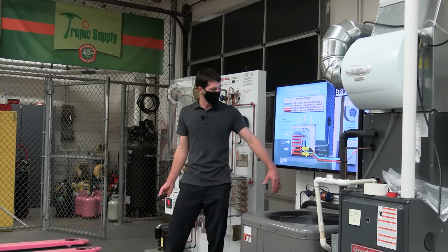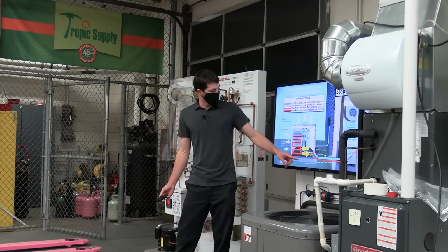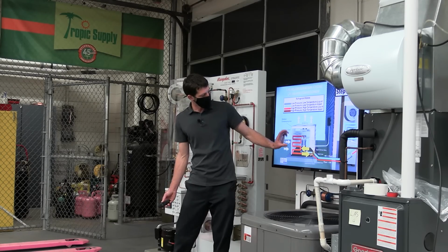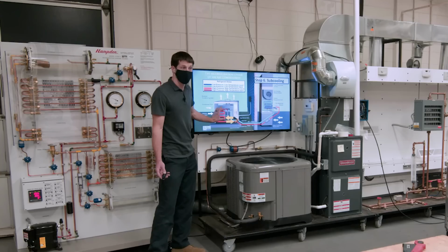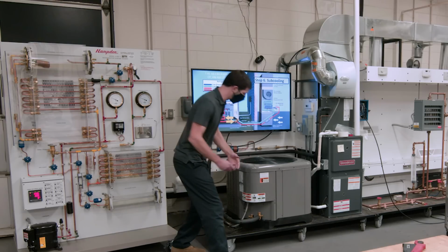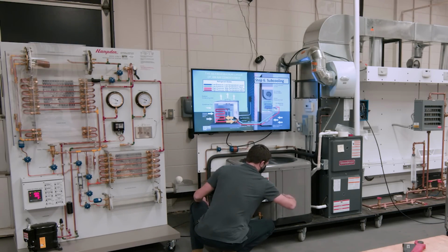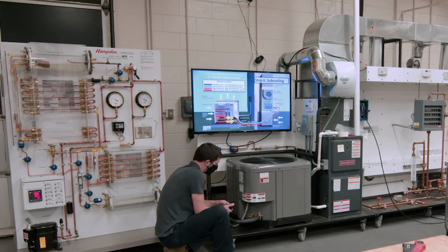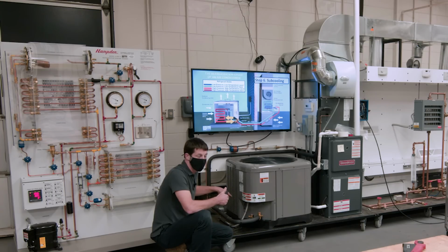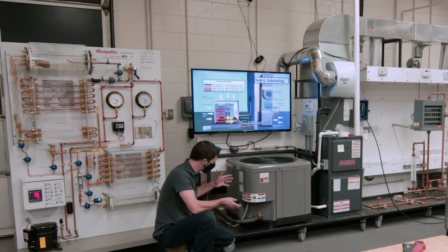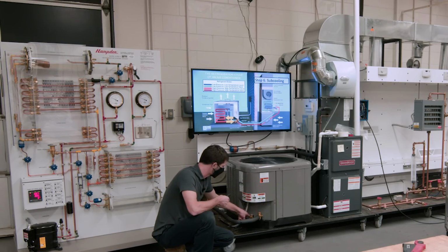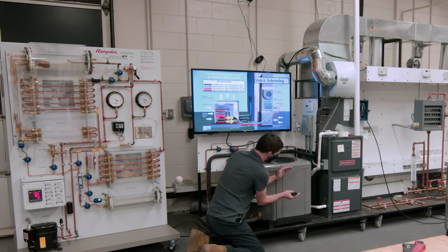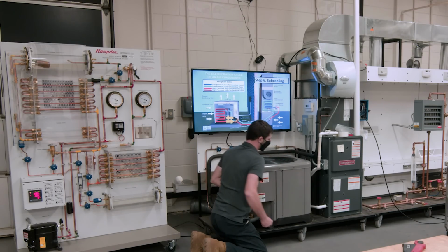So say it's R410A. What it's going to tell you is the temperature right here. I know it sounds odd because it's a distance away, right? It's flowing through all this, and then it's coming over to here. Your line temperature is going to be lower than your saturated temperature at the port. And that change in temperature, that's your subcooling.